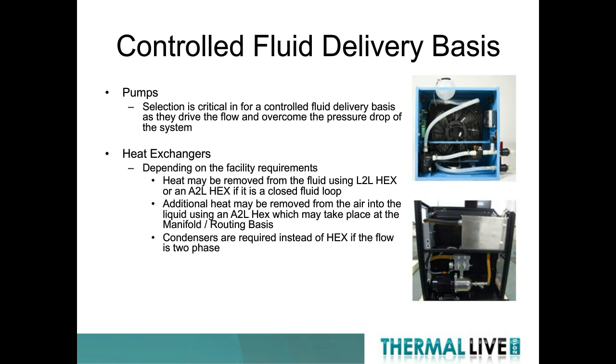And we also can see that the heat exchanger can be a condenser if this system is a two-phase system with vapor and liquid. So what I'm going through in our example is a single-phase liquid cooling system, but it very well can be a two-phase system. And so the heat exchanger essentially becomes a condenser in that model.